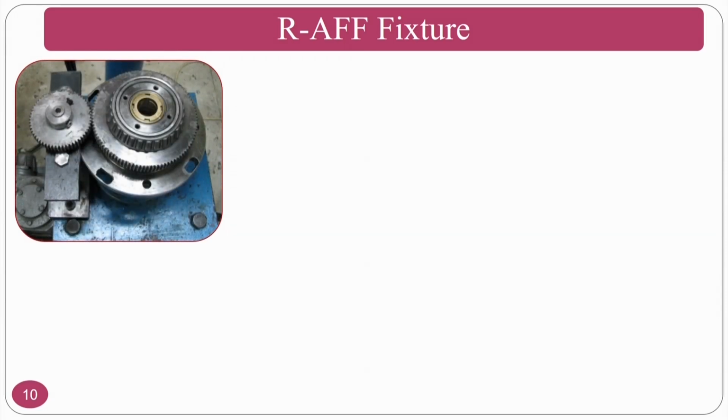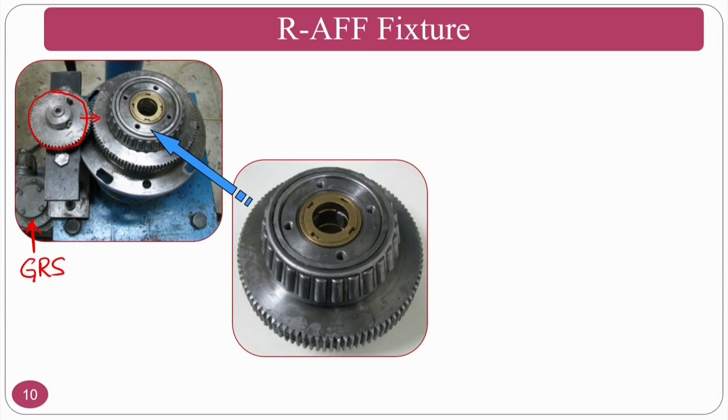Okay. The most important thing in this particular process, compared to the abrasive flow finishing process, is the fixture, how the fixture is designed and other things. If you see here, the gear reduction system is here. Okay. That is connected to another gear, and this is the driver gear, and this will be driven, wherein the workpieces are placed. Okay. Wherein the workpieces are placed, and you can see how the workpieces are placed.